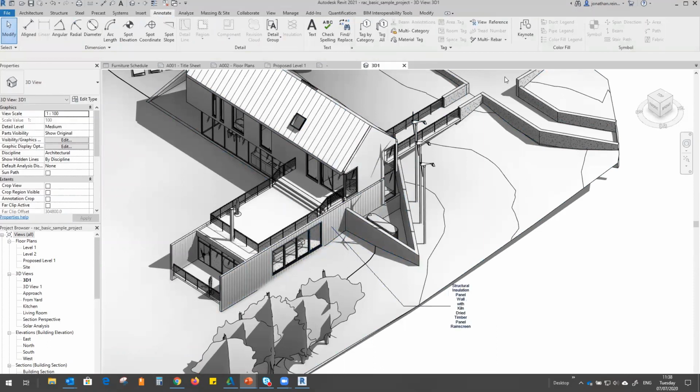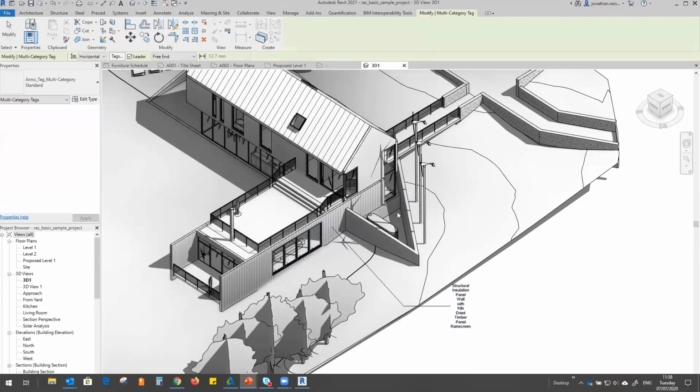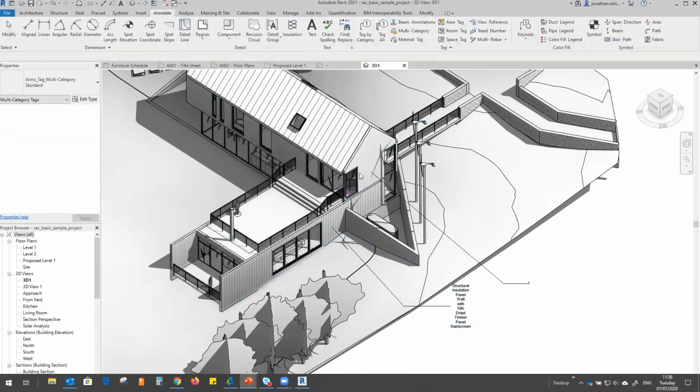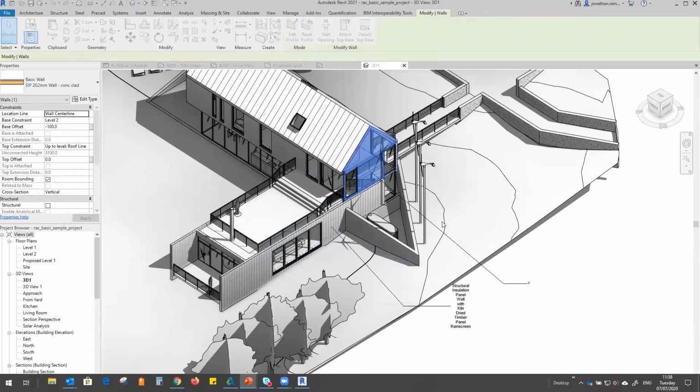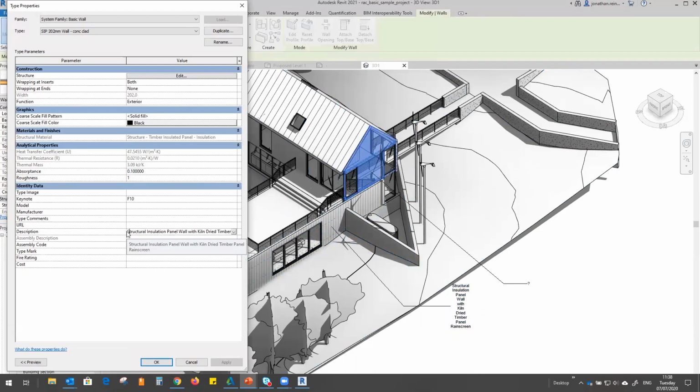It was only entered once, and if I enter that type of information on a window, on a different type of wall, that's a different type of wall. I can also go into this wall, and wherever that's placed, I can change the type comments. It's a very similar note actually. I'm just going to go into type comments, paste that in there, and you can also type your own custom. So these can be finishes or anything like that as well.